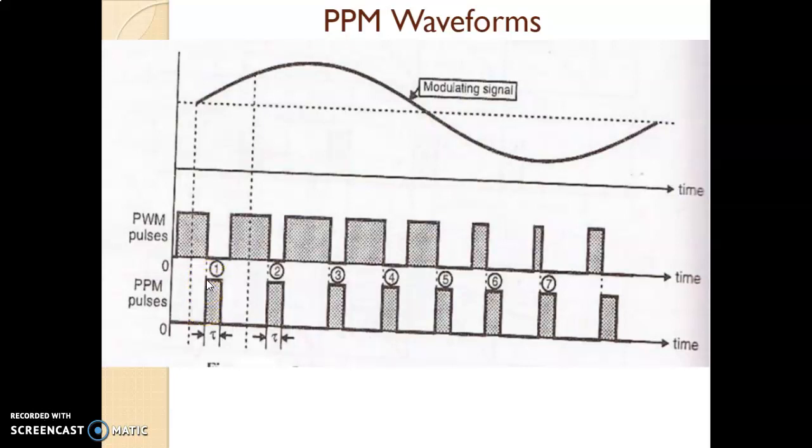It will remain in this high state for a certain period of time, which is calculated by the RC time constant, and after that time period is over, it will automatically return to its original position. So the monostable multivibrator is triggered, goes into the quasi-stable state, and automatically returns to the original state.